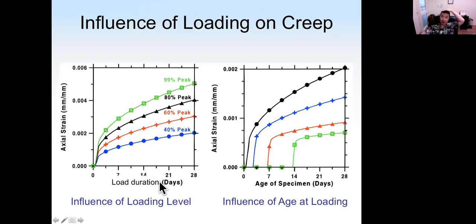Influence of loading on creep. Okay, so creep is caused by stress inside concrete. And that stress could come in from loading, could come in from shrinkage. Okay, so as a result, if we increase the amount of load, creep will be higher. Right, so it makes sense.